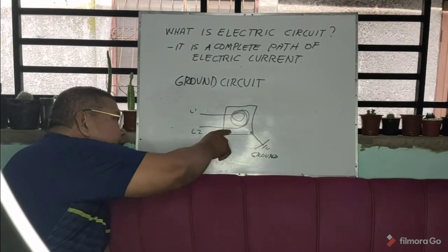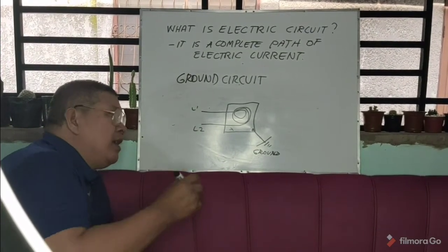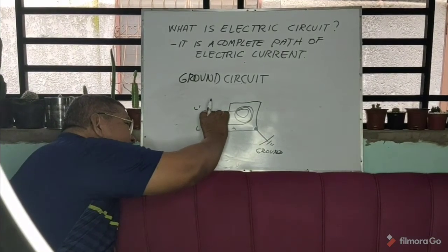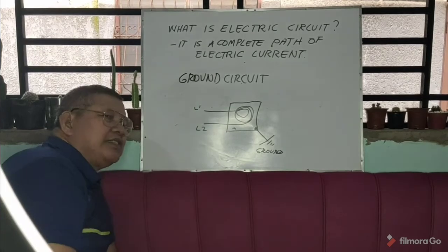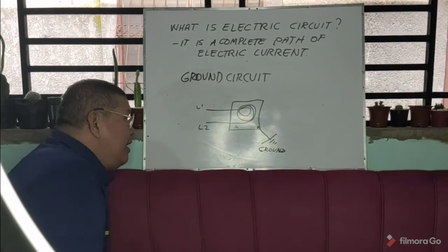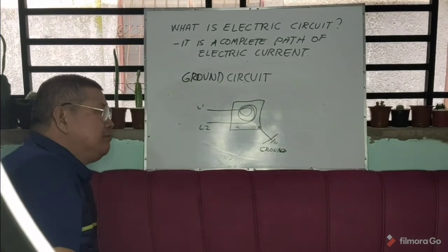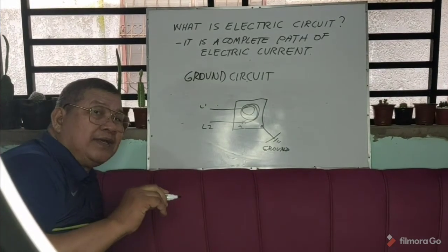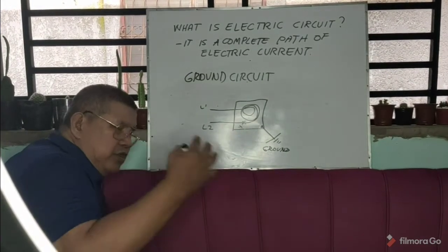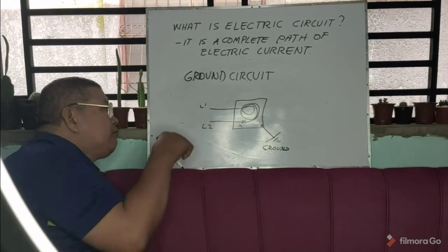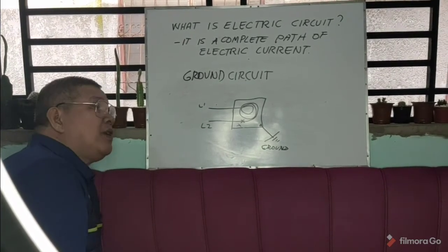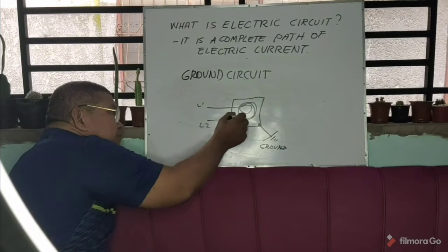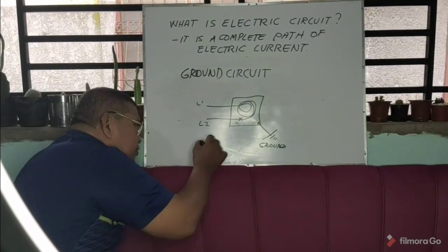Now you will know which line is grounded, because the wire becomes hot. Sometimes you just touch the wire and feel where the heat is, and that's the wire that is being grounded. So if you don't have the ground, and this one touches the frame, it is an open wire with no insulator, and if you touch it, you will be grounded. So what will you do next? Try to locate your ground again using your continuity tester. How would you test if this stove is grounded? You have your continuity tester here.